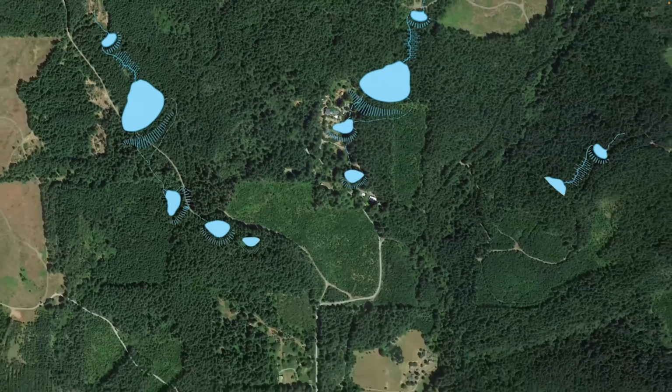So right away, it can be a good idea to put live stakes or woven bundles of willow and red stem dogwood or any other type of woody riparian plants that you have on hand to anchor that space. In the near term, those live stakes may not provide very adequate erosion control. So one way to go is to stake a bunch of rows on contour and then backfill with straw and other plant material and woven brush mattresses that can get embedded into the dirt there and will ultimately sprout and grow so that they create a permanent cover and erosion control.